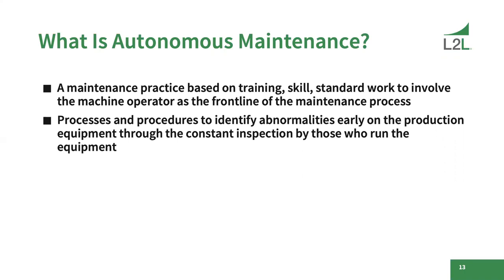Planned maintenance work is 4 to 10 times less expensive than reactive maintenance work. If I can train an operator that if you see odd looking metal dust coming out of a bearing, or if you hear a squeak or something like that, let us know early, and I can get that fixed in a planned manner, I can save a lot of time and a lot of money as opposed to just letting it fail.